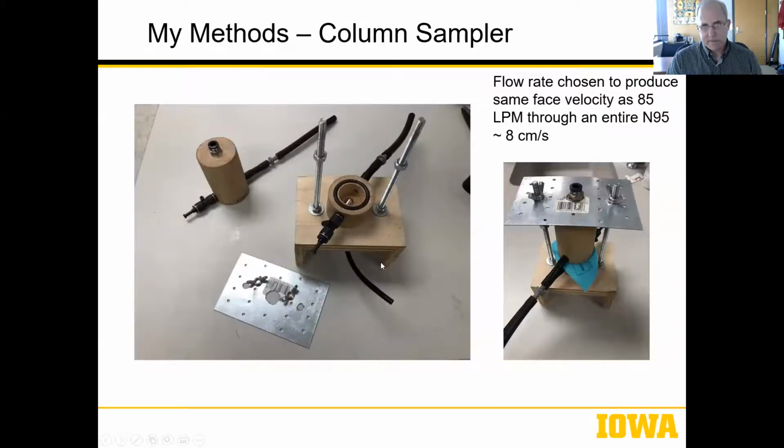Yes, and here it is. This was built in my garage with the lathe I have in there. I considered having somebody redo it in stainless steel or something nice looking like aluminum, but it wouldn't be any better, so it's never happened. So you can see there's an O-ring in here that is squished down when the top is squeezed down by this plate over the material. So it forms a very, very good seal. So there's no leakage around it. And you can then have air flow down through the top, and I can measure top and bottom, et cetera, to get an efficiency. Now notice 8 centimeters per second.